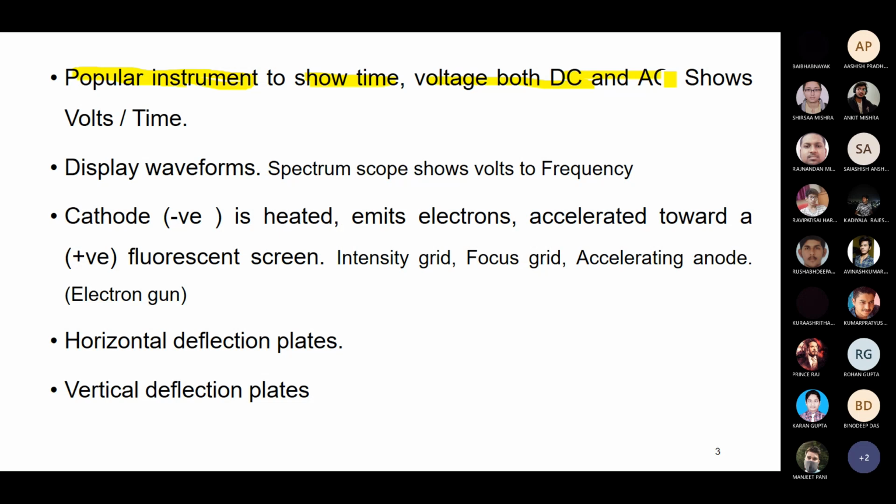Another thing, there is an arrow symbol. By this arrow symbol, anybody can understand which one is the ground. The color of the arrow will be the probe's channel color. There are 4 channels, so 4 different colors are there, as well as their ground color, and the waveform color will also be different based on the color combination. So you are able to see voltage as well as time. It displays the waveforms.